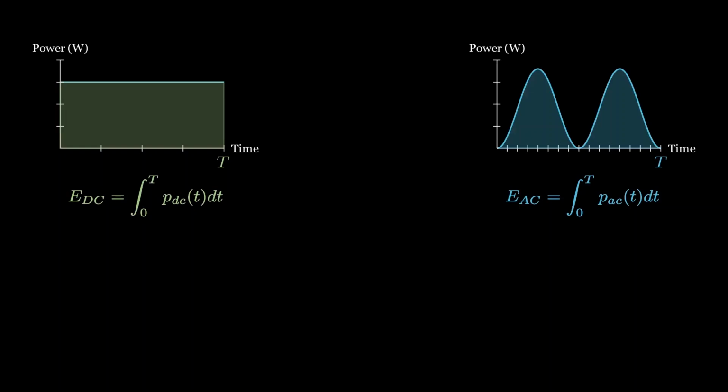T. To work out the energy in the DC circuit first, we will replace the power with V squared over R. The power is constant, as we discussed earlier, so we can take it out of the integral. The integral of 1 over 1 periodic cycle simply becomes T. Finally, we will just call the voltage in this formula V effective from now on.